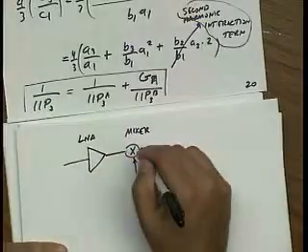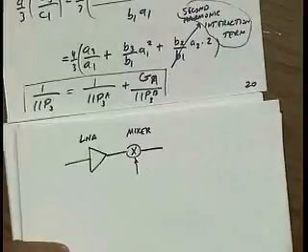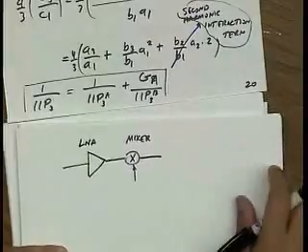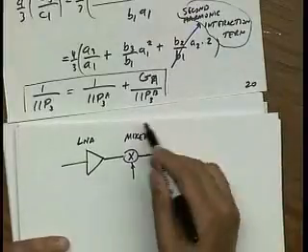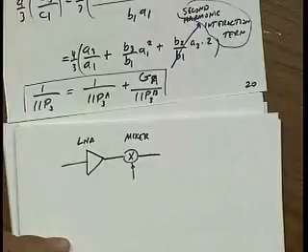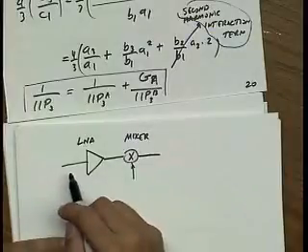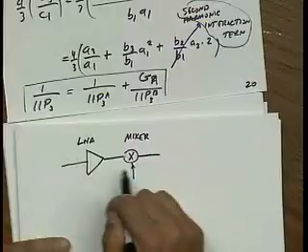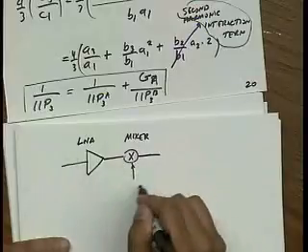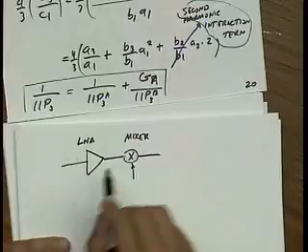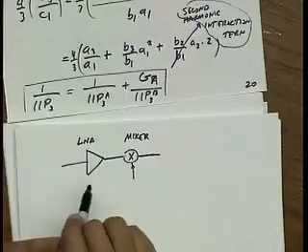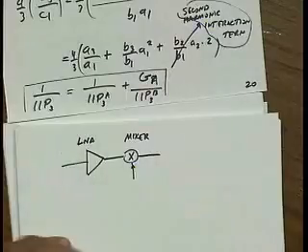And you'll find out later on that mixers tend to be pretty nonlinear. It's pretty hard to design a very linear mixer. So this will have a pretty low input IP3. And if I input refer that, that's going to be even lower. So I may get into a situation very easily where, if I don't pick my components right, the linearity of the whole system is dominated by the linearity of the mixer.